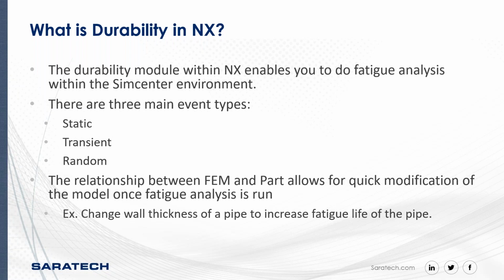So let's say you did your fatigue analysis and you realize that something, let's say a wall thickness, needs to be thickened. You can simply go back into the model with one click, go back, change the thickness, move back into the Simcenter environment, and hit update and rerun your model.